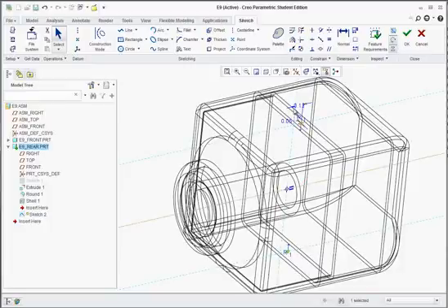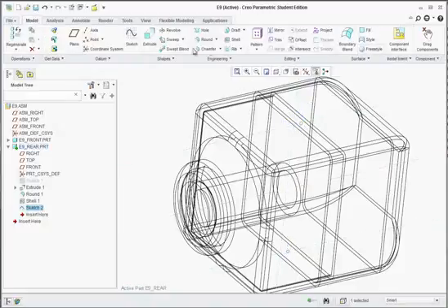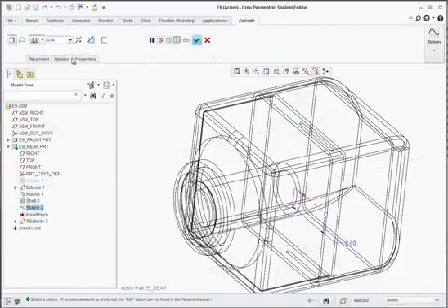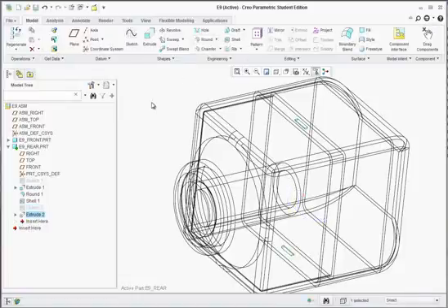Okay, at this point, we can now extrude this 0.25 thick from the mid-plane. So we go to extrude, select mid-plane, which is right here. It extrudes on both sides, and it's going to be 0.25 wide. Hit the green check mark to apply.